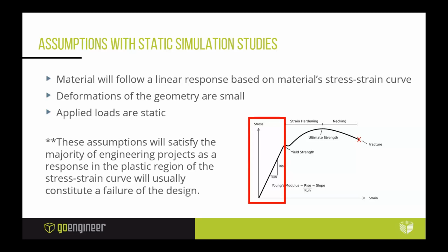So what that's telling you is that you're now probably flirting with the boundary between a linear response and maybe a nonlinear response of a model, because it sees that it's projecting a larger displacement. I'll talk a little bit about that, what that means and how to maybe deal with that situation, a little later. But just know that's our second assumption. The third assumption is pretty self-explanatory: all of the applied loads are static.